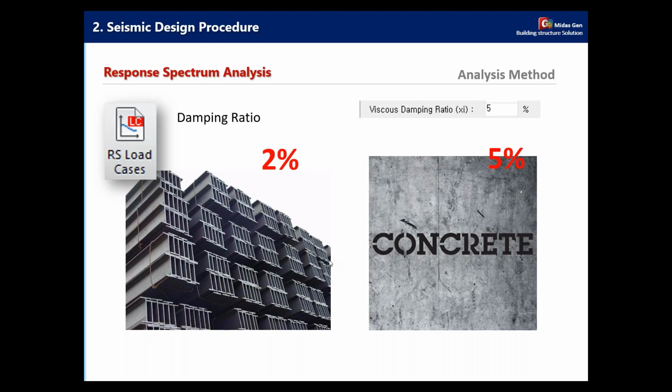And for the composite material, you can define separately the damping ratio in the software, and the software will analyze the damping of the composite material you are going to use. If you are using steel-concrete composite, you can specify their damping ratios, and then the software will calculate the damping of both materials using the energy method that we are going to see in the software very soon.